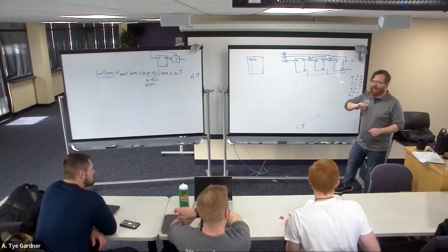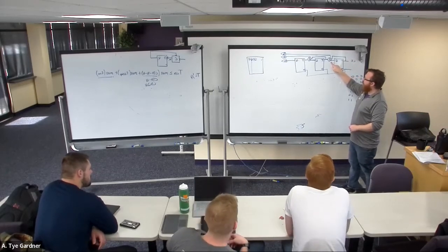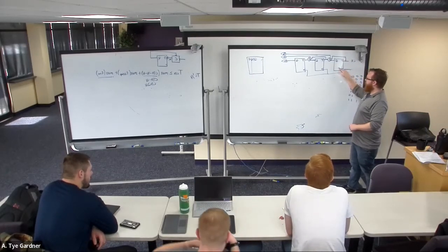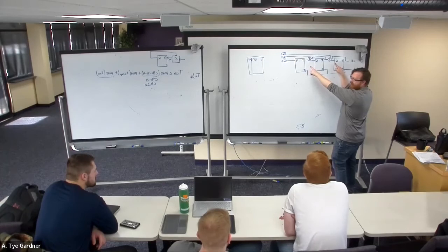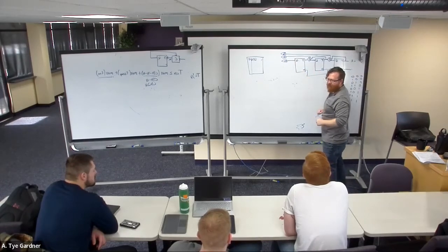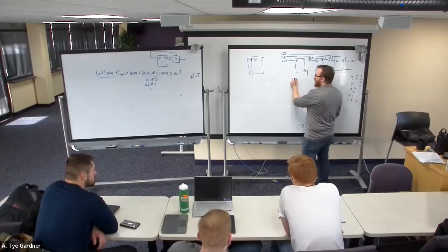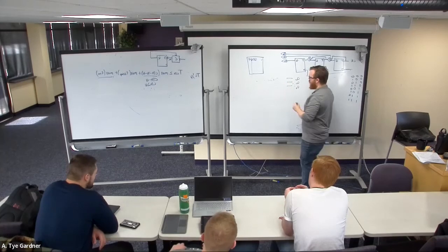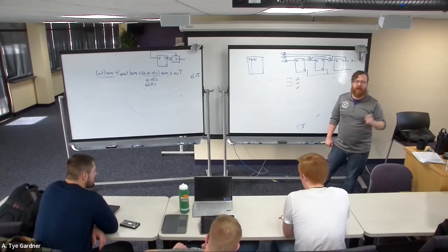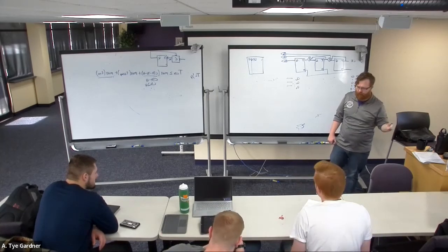It can only go so fast because this clock enable is what's going to happen is this one will update after 1 clock to Q delay, but this one will update until another clock to Q delay, and this one will update till another clock to Q delay. So let's say that we're at the Q0, Q1, Q2, and we're starting at the 111 state, right? And if I add one more to that, they're all going to toggle, right? And so we're going to go back to 0, 0, 0.